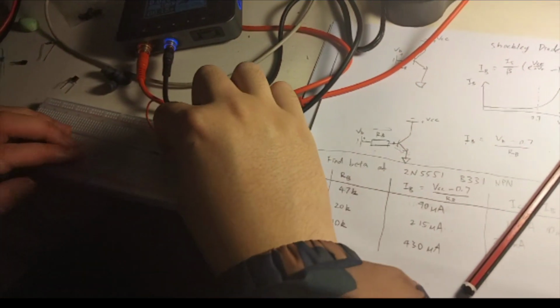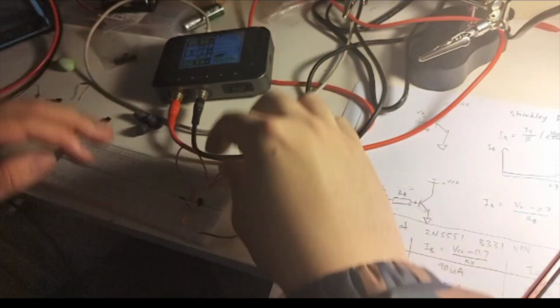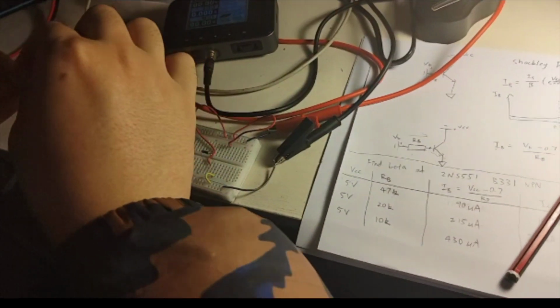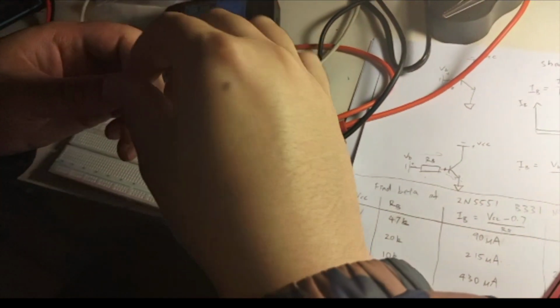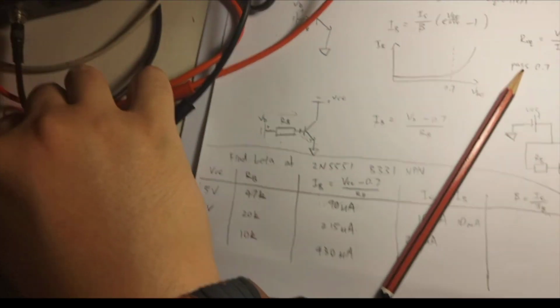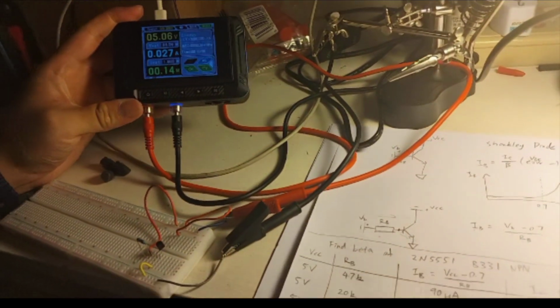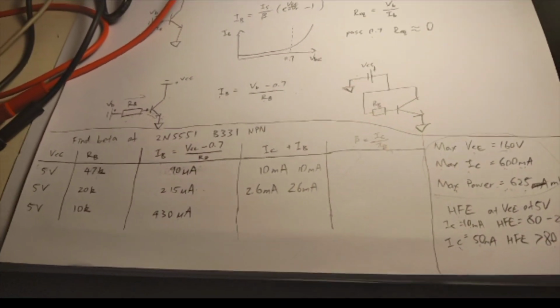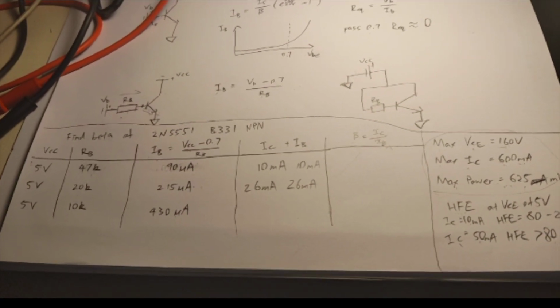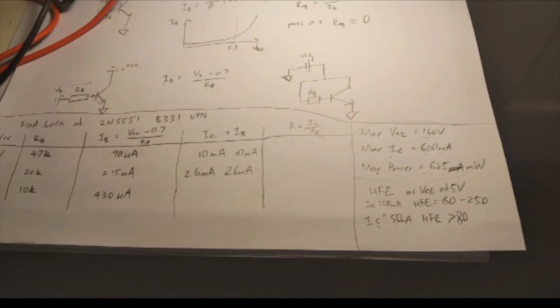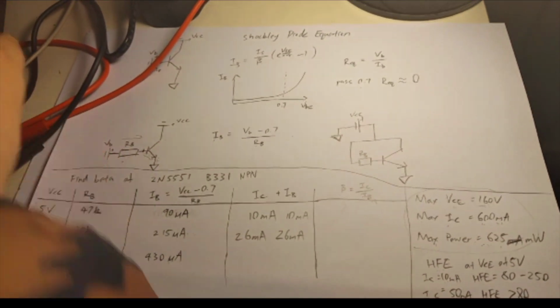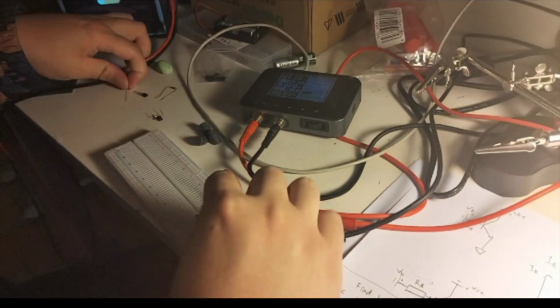And yep, let's test it with the other transistor now. Make sure that they're not that different. Again, we get 26 milliamps. It's very consistent on the same batch. So this is apparently what you find with transistors of the same batch, is they have a similar hFE, but the same brand of transistors on different batches can have wildly different hFEs.